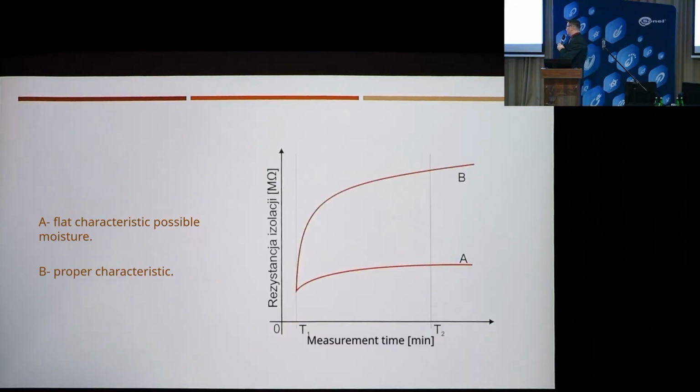Along with these changes that occur in the process of measuring insulation resistance, we can analyze how capacitance and polarization affect the way our indicated insulation resistance rises. Based on that, we can draw various conclusions. It's not so bad if we're taking measurements regularly, for example, on cables, and by comparing them we know whether the insulation is degrading or not, whether those results are changing or not.